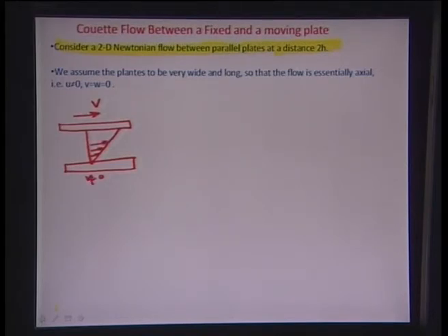Let us say the velocity of the fluid is a parameter u for convenience's sake. So you have u equal to 0 here because of this zone of no slip, and then the velocity slowly increases to u equal to v, the velocity of the plate here.